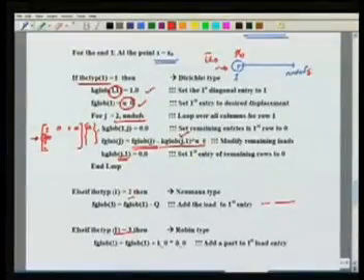Next is, if I want to have a Neumann boundary condition at this end, that is at this end I have a force Q applied. Q is tensile. So in that case, life is very simple. I simply go to the first load vector entry, from which I subtract Q. This modifies the first global load vector entry, okay, and I have taken care of Q. If you remember, this is what we needed from our variational formulation.